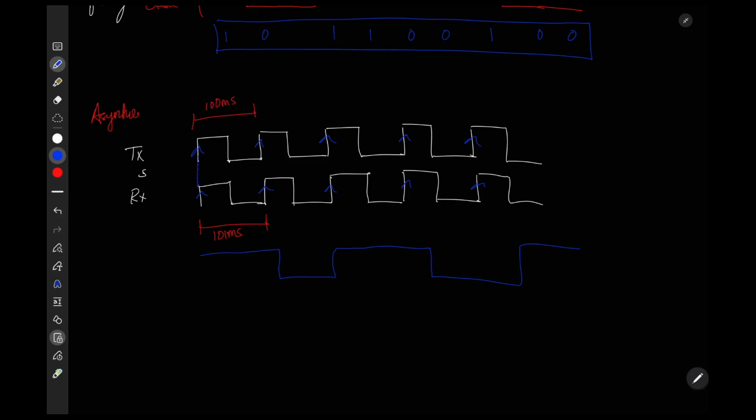and the second cycle, because the periods of the clocks are slightly different, each period there will be a 1 millisecond phase difference. So the next cycle there will be a 2 millisecond phase difference. Because the frequencies are absolutely close together, each cycle will add a minute error, it will be an aggregate. The error keeps on getting larger and larger after each clock cycle. So after 3 clock cycles, there is a mismatch between the rising edges of 3 milliseconds.